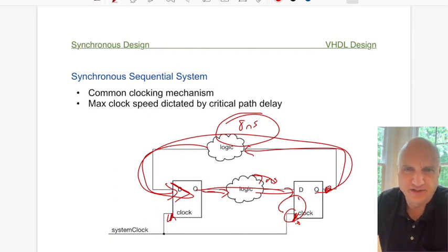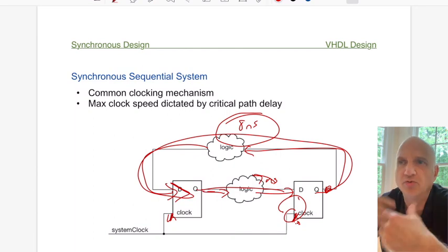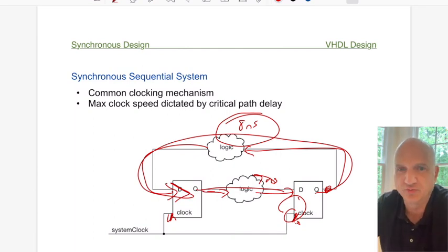Technically, in design for sequential systems, you don't have to have just one clock. You don't have to have a single clock system. You can actually derive multiple clocks and run those multiple clocks in your system at the same time. It's an incredibly complex thing to do, and it's not very common. Okay, some more advanced designs might do it. It's useful for reducing power consumption in some parts of the chip, but the idea of a multi-clock system opens up a whole can of worms as far as how do you synchronize one set of the design with the other set of the design, and that's kind of beyond the scope of the course that we're doing.